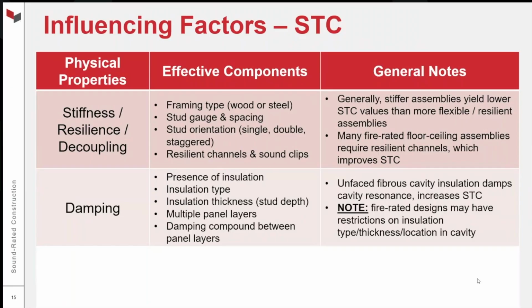through an assembly. On the right in the notes, we say unfaced fibrous cavity insulation damps cavity resonance. That increases STC. I'm going to show you an example of that. And keep in mind that fire resistance designs, especially horizontal assemblies, may have very strict limitations or restrictions or caveats related to insulation type, thickness, and location in the cavity. So it's really important to follow and defer to the published designs, UL designs, GA designs, whatever they may be, especially for horizontal assemblies as it relates to insulation.